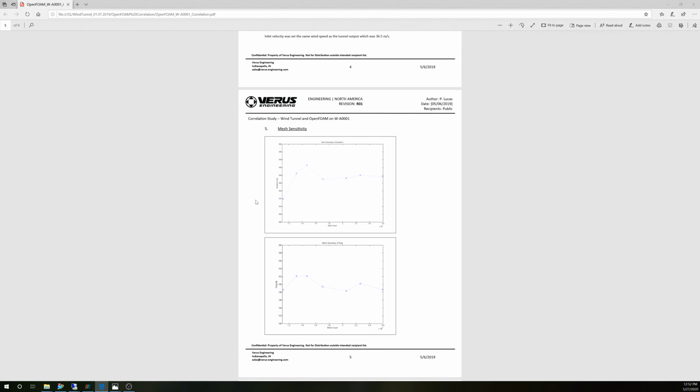This is specifically on OpenFOAM right now. The graph before was on Fluent. I don't really use the K-Epsilon realizable model in OpenFOAM. Actually, I've never used it in OpenFOAM, and I used it very rarely in Fluent. I do use the SA model though, and the K-Omega SST, and those still work. So that's a broad overview of the thing.